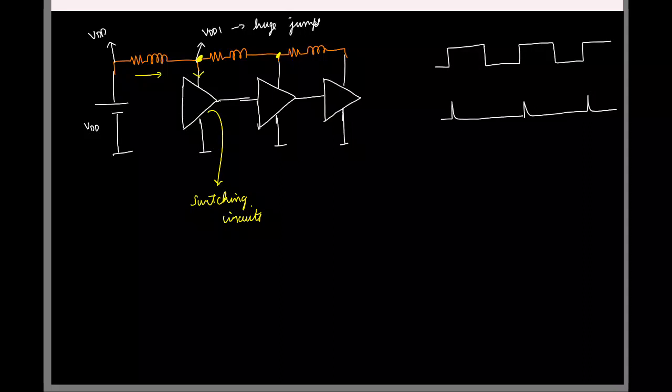Makes sense? These currents are essentially very high frequency currents. So you should provide a low impedance path for this current so that the currents will prefer that path, a lower impedance compared to this branch. So you should put something such that it offers a low impedance for these high frequencies.